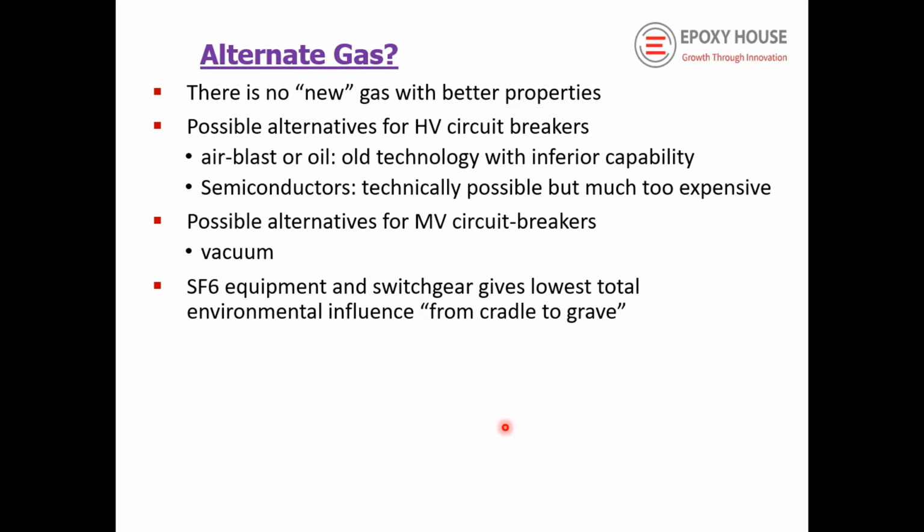It is commercially available up to about 145 kV. So up to 145 kV, SF6 gas can be fully replaced with vacuum circuit breaker technology and any other alternate positive pressure gas. Yeah, we can use it depending upon the electric field intensity on the surface of the conductor. We can modify it to improve, and it can be used for the circuit breaker up to 145 kV. So we can hugely reduce the usage of SF6 gas by using the vacuum interrupter technology up to 145 kV. More than that, we have to find the alternate gases.